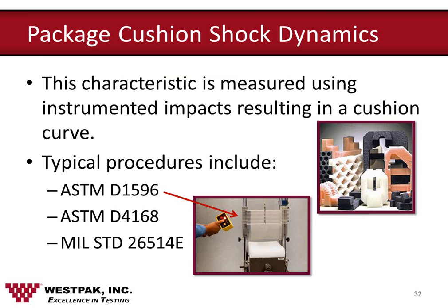In this procedure, the cushion material is impacted with a platen of known mass and known velocity. The actual procedure looks like this. The end result, the deceleration level experienced by the platen, is recorded. This procedure is repeated a total of 5 times, and the mass of the platen is then changed in order to change the static loading, and the process is repeated.